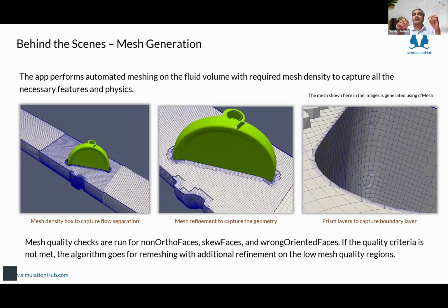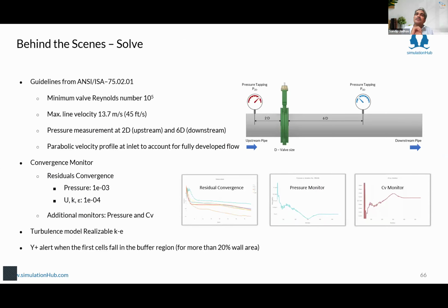That is done for all, I would say, 24 simulations that might be there, because with the flow our mesh type also changes. So there are really detailed ways that we adjust and accommodate the mesh requirement to meet the physics requirement.